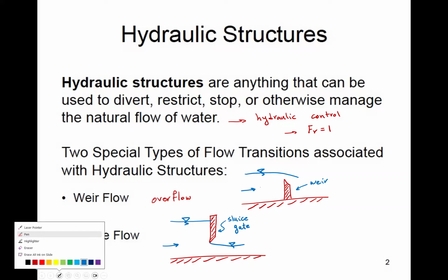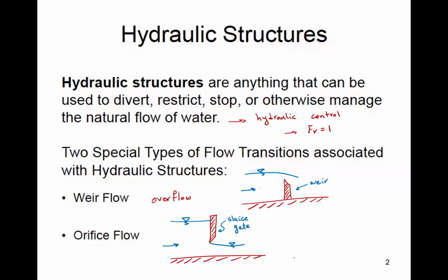There could be another case, let's mention that too, could be a case where you have almost a combination of the two, meaning that almost like you have a weir, and then you have almost like a gate on top. So you only have an opening kind of halfway up in the flow. So if that's the flow left to right, it has to go through this opening, this orifice. This would be an orifice. So all different situations, overflow, underflow, and almost a combination. So we'll look at these and see what is happening in them in terms of the hydraulics.